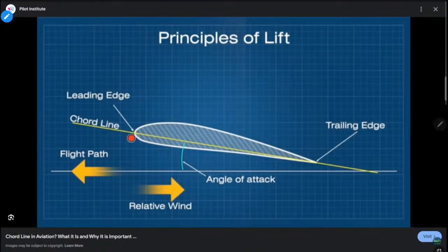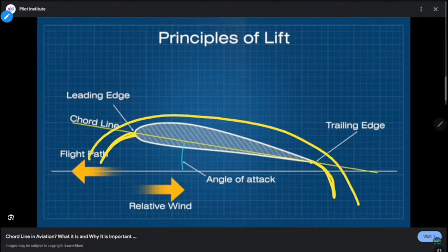So if you look at the wing, that's the chord line. The leading edge flaps will extend outward this way, and the trailing edge flaps extend out this way. And in essence, then you've got yourself a bigger wing for better lift. Now this is great during takeoff and landing because now you can have higher lift at lower airspeed. That's the name of the game. And then when you're at full cruising altitude, you fold everything back in and have a nice clean configuration.